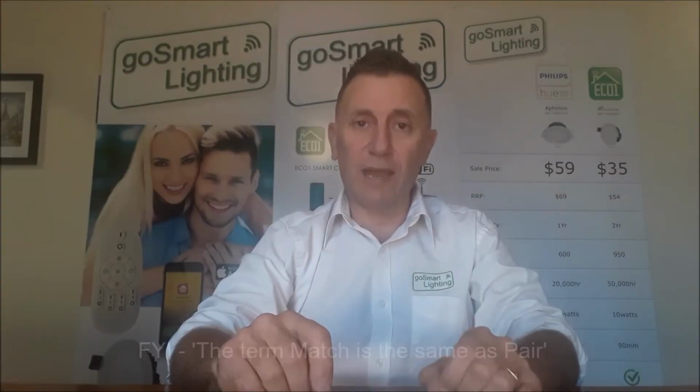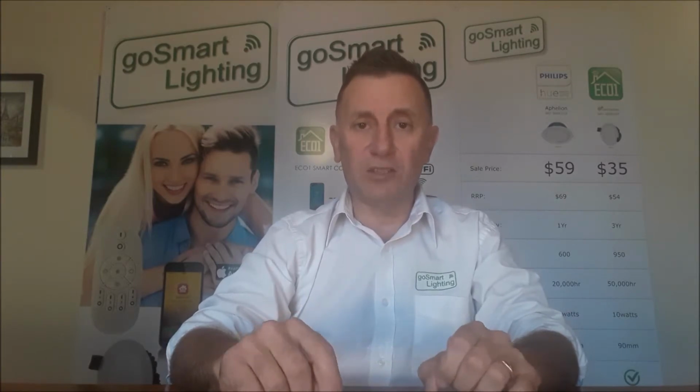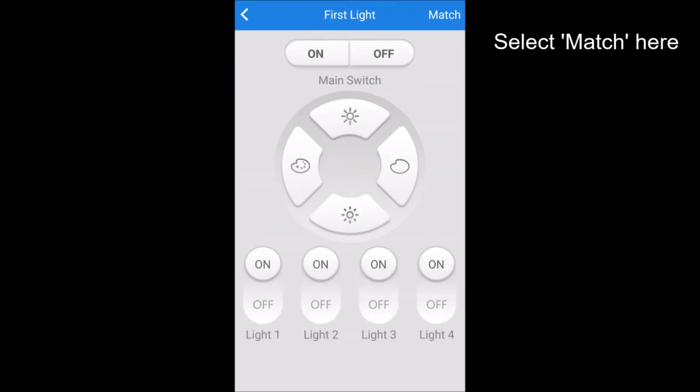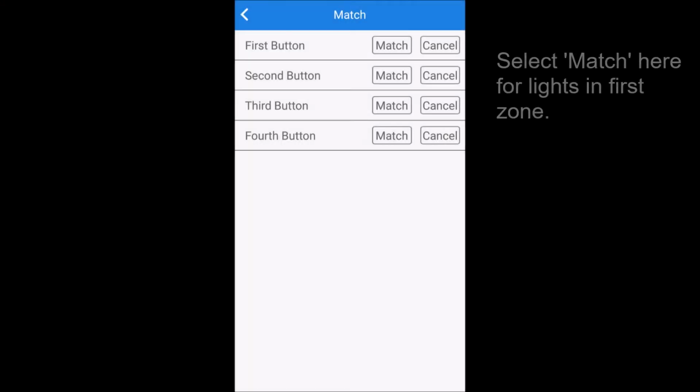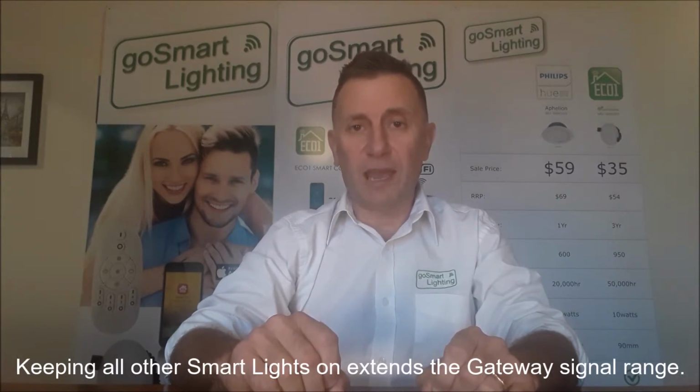The next step is to match your lights to this lighting control. So click your lighting control, and this is what screen you should see next. Now click Match next to the first button, and this is what you should see. Now go ahead and turn your light switch off if it's not already, and then turn it back on. You should find that your lights flash slowly 3 times, and then you can press the back button on your